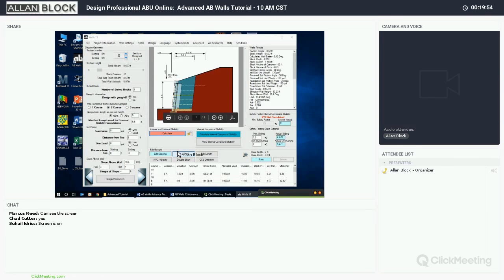A couple different ways to do that. You can always cut the block in 4-inch square and put a T in the drain and come through the face. You've got to be careful, because we always like to put some type of a rodent screen or some type of a screen in there. A real slick option, if you want to write this down, is called Wall Drain Pro, and I'll include this in the follow-up email as well.